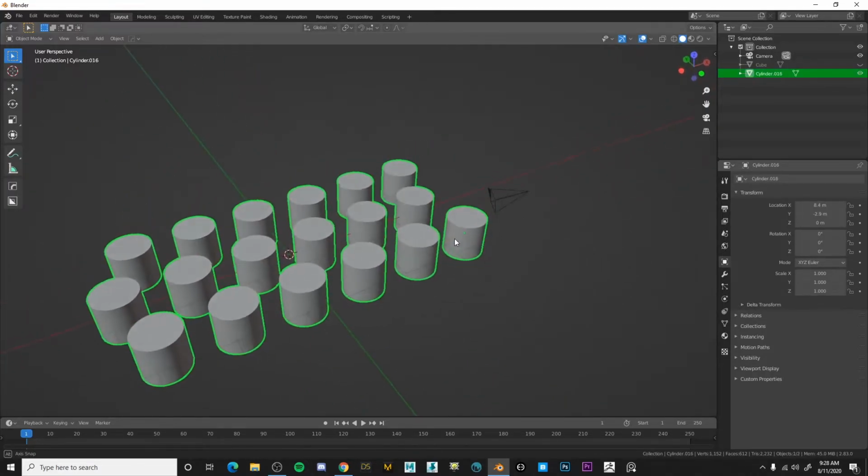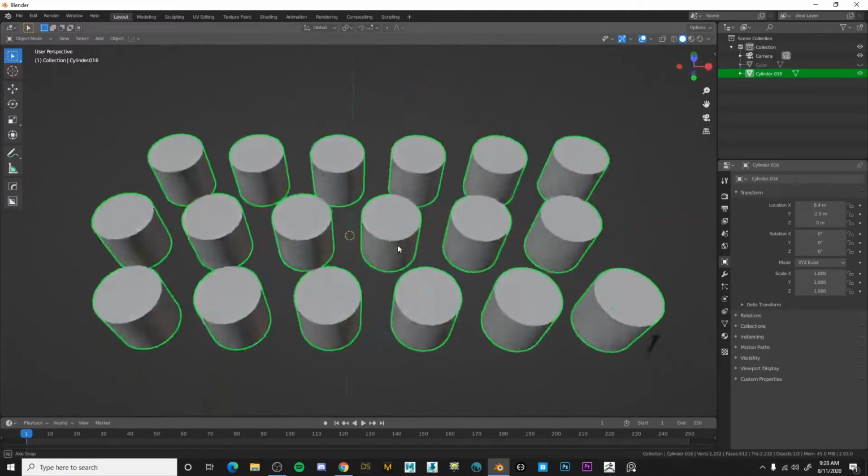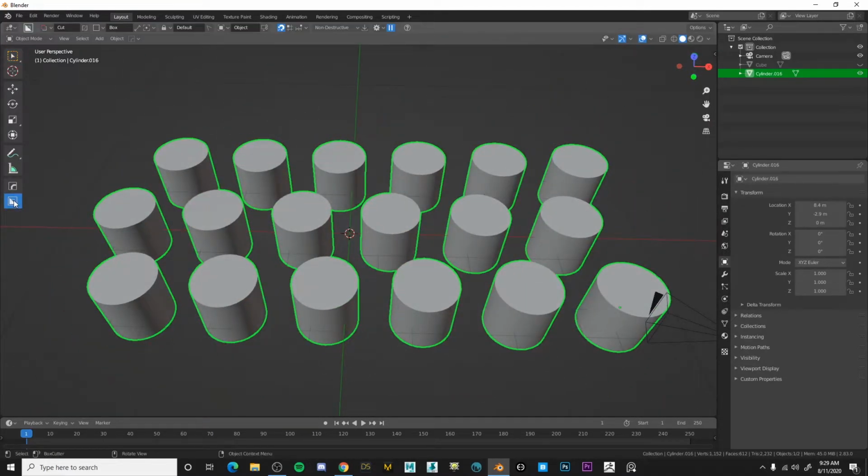So I merged everything into one single object, and what I'll do is go to Boxcutter and press D. D is the actual menu. You'll use D 90% of the time while using Boxcutter. Just press D and you'll get most of the settings here. Now I'm going to press Custom, and on top there will be a new setting, this plus sign on a sheet. Just press on that.